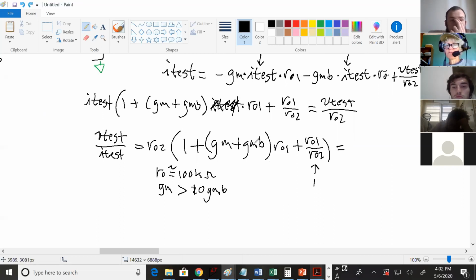Okay, what about GM and GMB? What's left there? Just GM. Yes, so what you end up with is GM times RO1 times RO2. Okay, and the whole goal of this story was, even though I'm 3 minutes over, so sorry again, that when you had a single transistor, remember when you did the analysis, you got that it was RO?